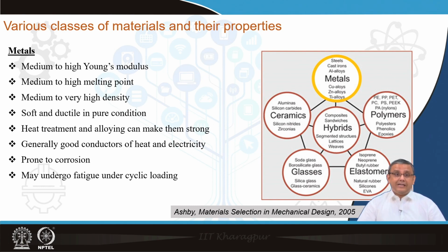Also aluminum alloys, through precipitation hardening or cold working, can actually provide a wide range of strength. Because of the availability of free electrons, which are kind of charge carriers, metals are good conductors of heat and electricity. That is why metals typically possess a high conductivity, like copper or silver, which have extremely high conductivity, but as more defects are added into metals, the conductivity goes down.